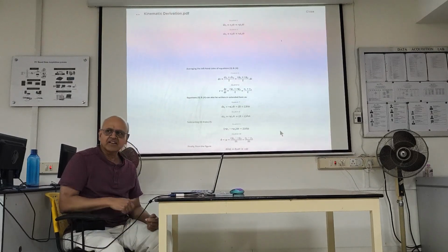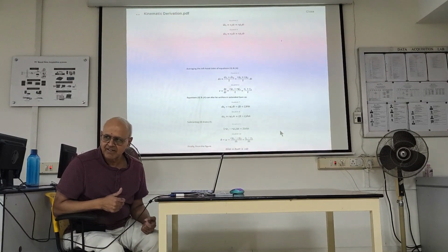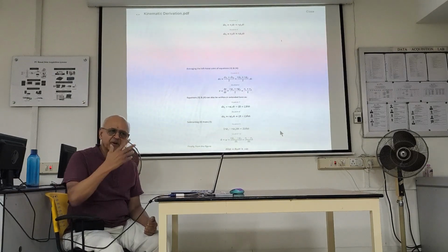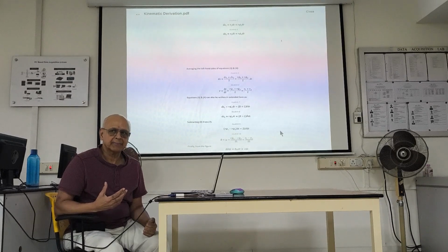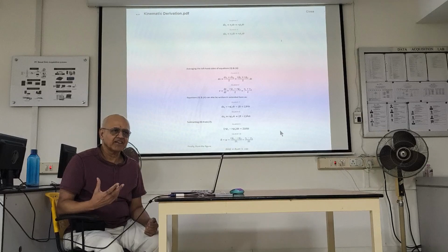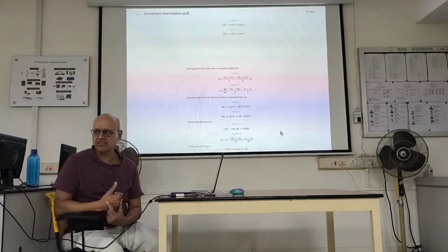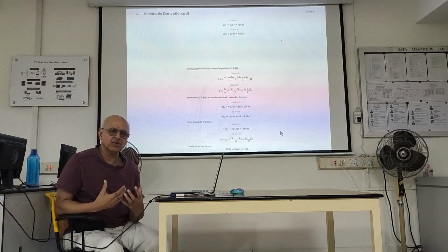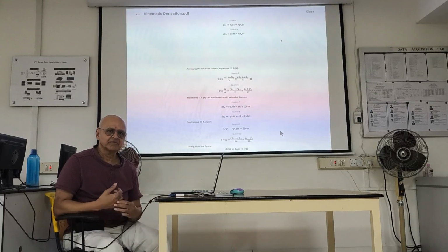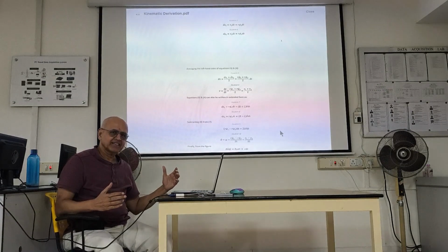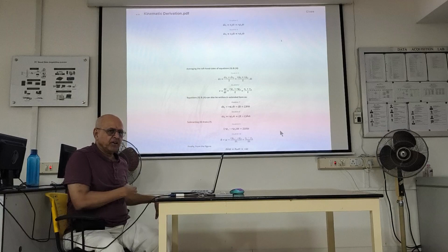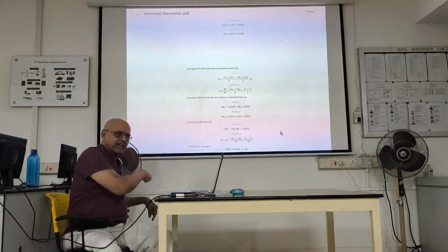It's right here. What is the radius of curvature? Go to the formula, V by omega. 0, right? It is 0. So when you're spinning, the radius of curvature is 0. Now, is that good or bad for a vehicle's ability to maneuver? Can a car go this way? Suppose the car has to reach some spots here. It may not be able to go there. It might have to drive out and come back, right?